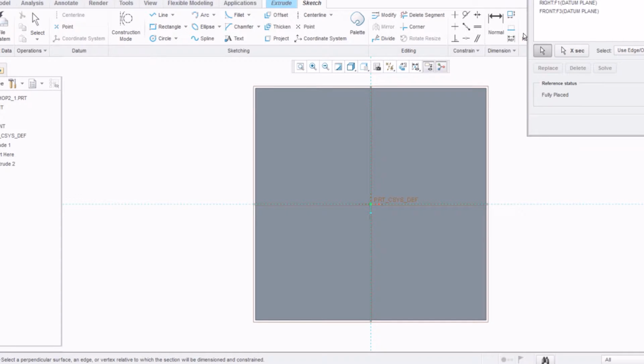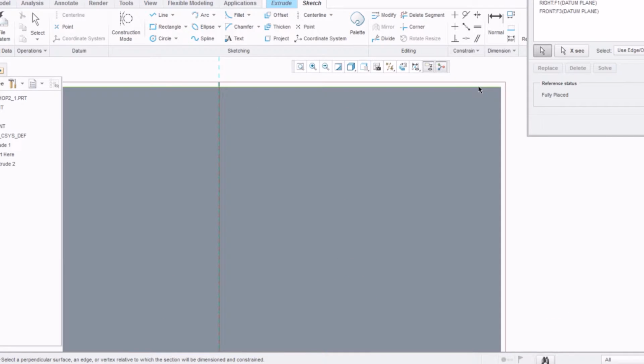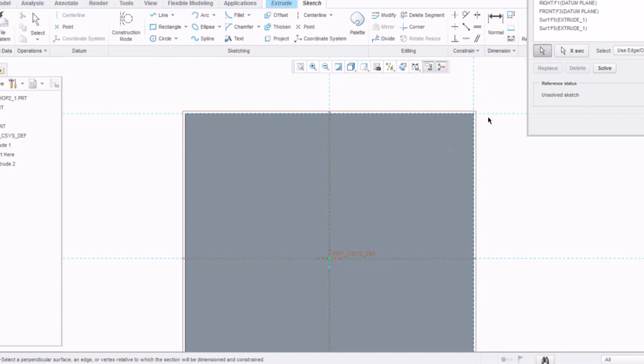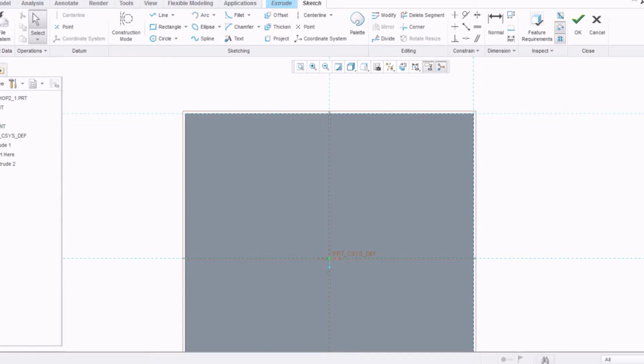So if we wanted to reference that corner, what we do is, if this is not already clicked in, click this once, come over, find the corner, you'll see it turns green, it's hard to tell. It says surface, click once, and now you see we've referenced that surface. And find the other surface, click that surface as well. Once you've done that, you see the 2 surfaces there. Now you can see 2 dotted lines, just like the others. Click close.